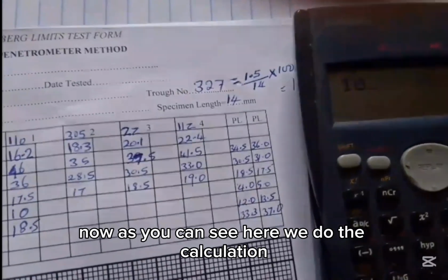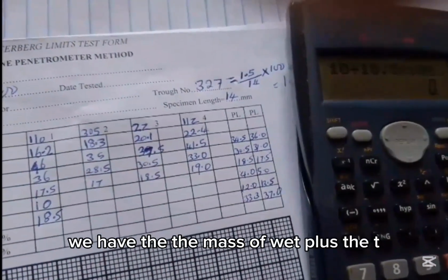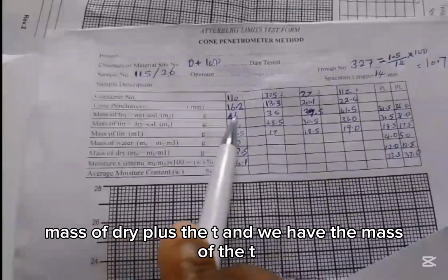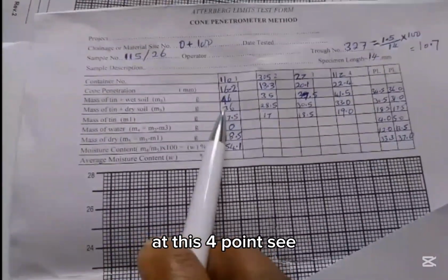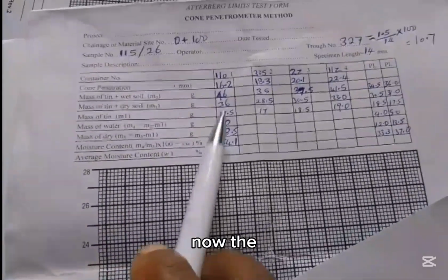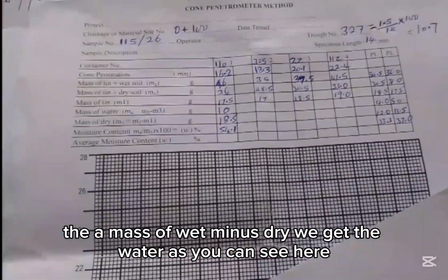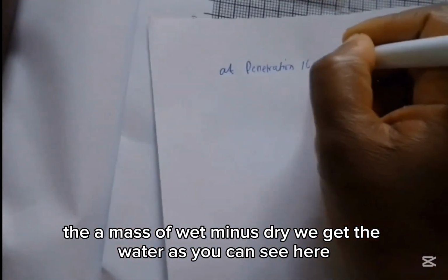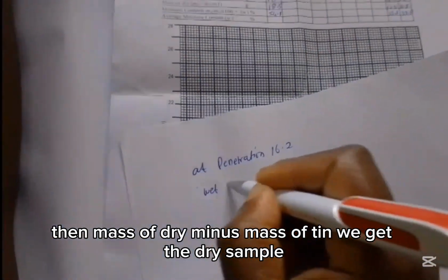Now as you can see here, we're doing the calculation. We have the mass of wet plus the tin, mass of dry plus the tin, and we have the mass of the tin that will help us to calculate all the moisture content at these 4 points. See now, the mass of wet minus dry, we get the water, as you can see here. Then mass of dry minus mass of tin, you get the dry sample.